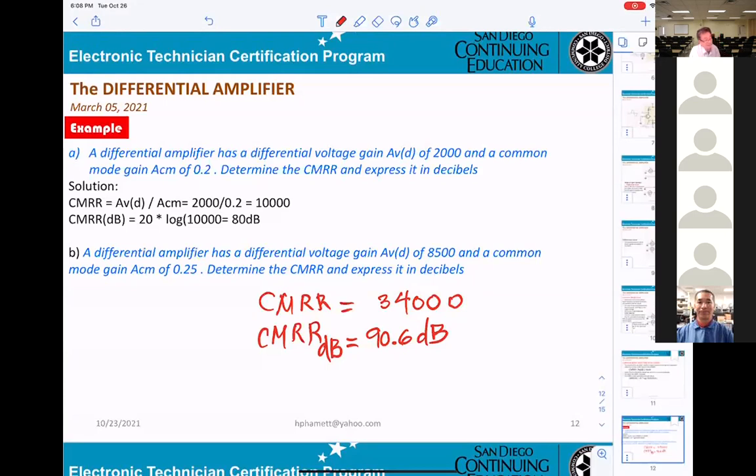Yeah, you want a high common mode rejection. Common mode rejection is basically the ratio between the gain of the differential amplifier and the gain of the noise. If they are equal, the noise and the signal will be the same at the output. Normally the input to the differential amplifier can be microvolt or millivolt peak to peak.